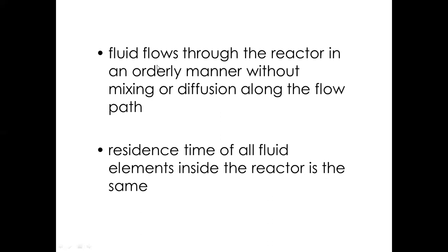It's as if the fluid elements inside your plug flow reactor are moving in an orderly manner without mixing or diffusion along the flow path, which is along the axis also. However, we expect that as it moves along the axis, the concentration changes. So there are axial changes in concentration, but not radial.